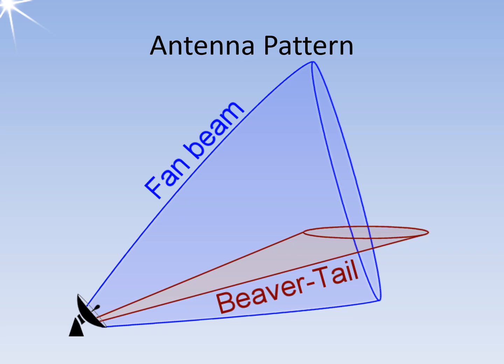Nodding height finders and omnidirectional rotating radars work together in a network to jointly measure three-dimensional coordinates. In air traffic control, the precision approach radar uses both diagrams to safely talk down the approaching aircraft. Both diagrams swivel in a small sector to detect whether the approaching aircraft is directly on the glide path.